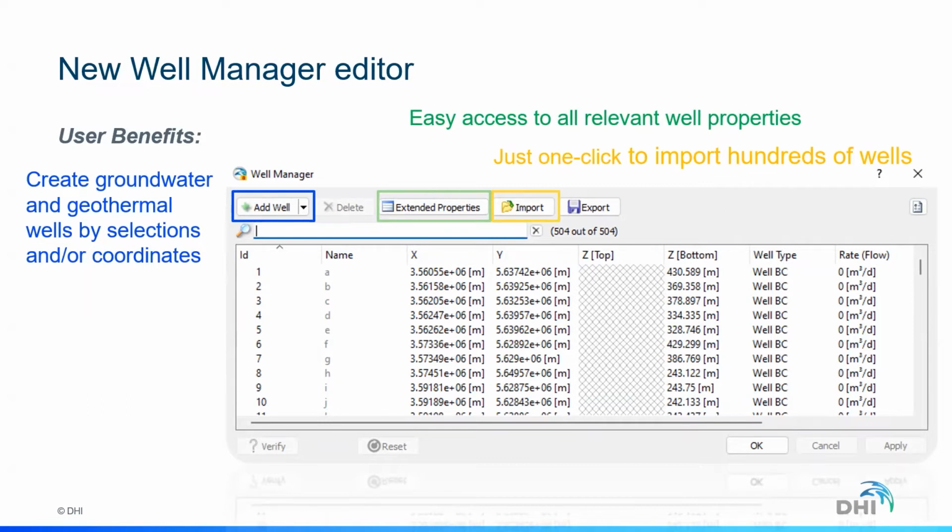So we have a number of routines to evaluate or run neighborhood relationships. Here, it's not just a table, it also runs a number of checks which are not available in other parts of the FEFLOW code, which evaluate if there is no conflict between existing boundaries or if the elevation of the well is maybe above or below the topography. These are the basic examples, but there are a number more checks. It will help you to automatically check all this.